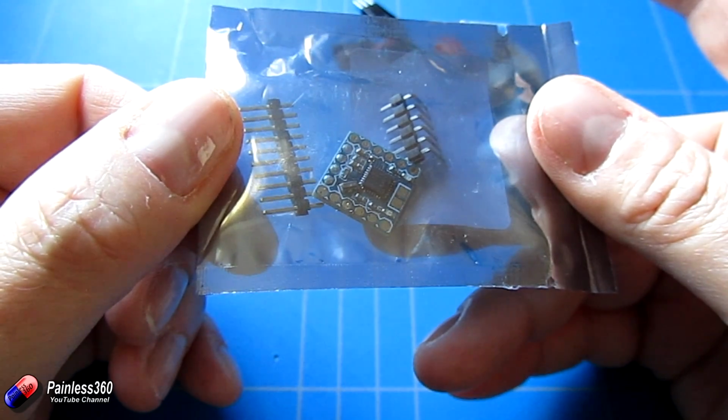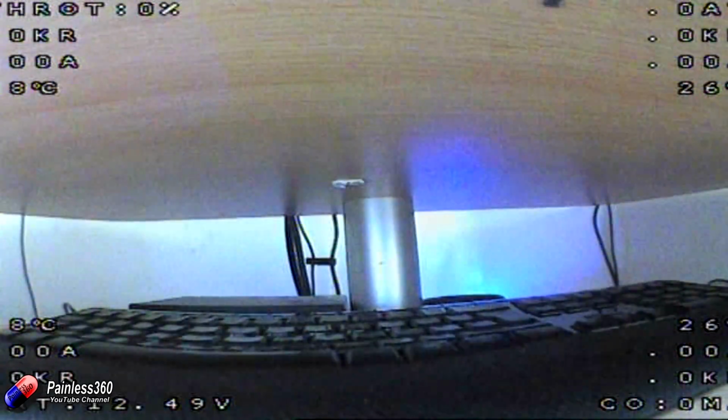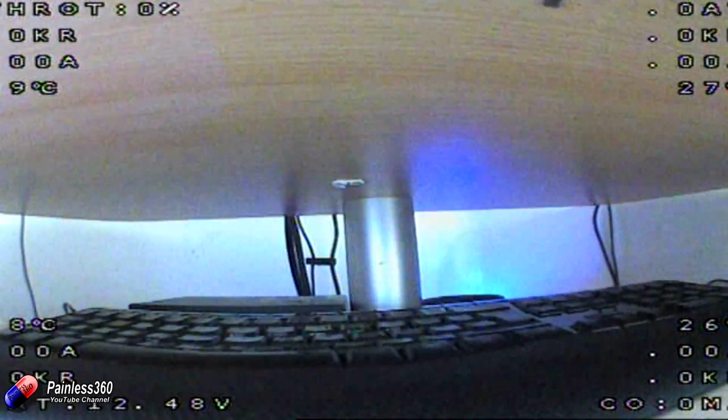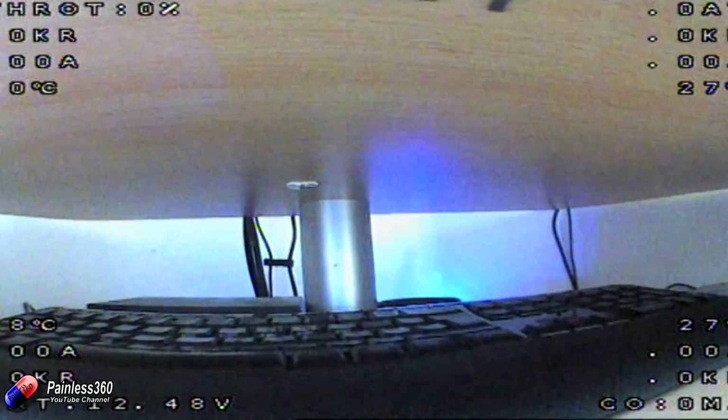Now, what it actually looks like in use at the end is in each corner of the image you have the status from each of the ESCs. Now, as we've already talked about, there is a very clever single wire telemetry connection that connects all the parts of the KISS system together, so the ESCs are constantly talking to the flight controller about their temperature, how much current they're pulling and everything else, and that is presented in each corner along with a bit of a summary down at the bottom as well on what's actually going on.